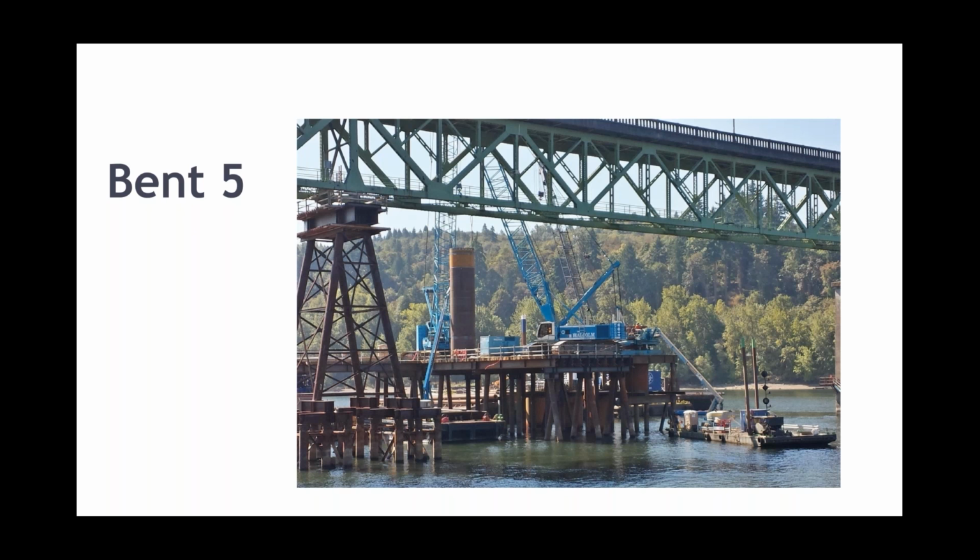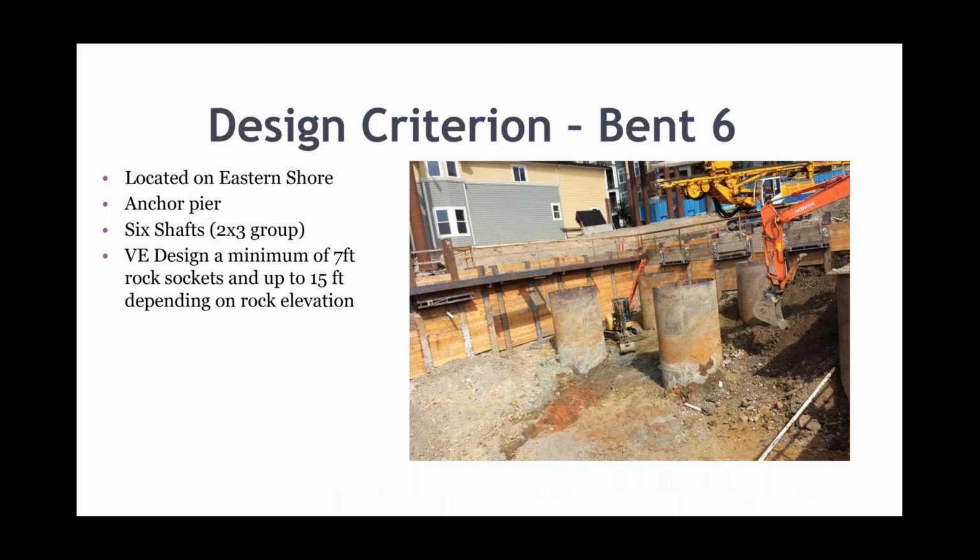So if the trestle is not designed properly for these giant lateral loads that are placed way up high in the air, basically above the point of fixity, very large deflections of that trestle occur, which has direct safety implications, but they also can play havoc on the alignment of the casing and further increase the risk of getting your casing stuck. So if you're designing an oscillator job or you're working on an oscillator job, make sure you think about the deflection of the bridge, of the trestle.